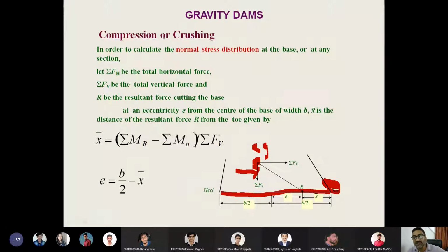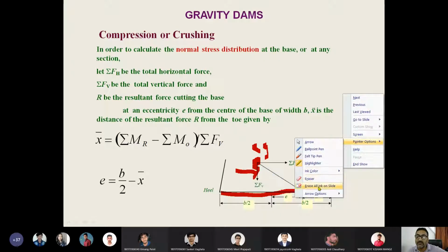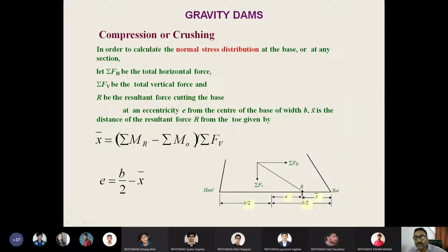Here in crushing, what it states is that this resultant force R, if it is within or inside the toe, like here, then it's okay, your design is okay.